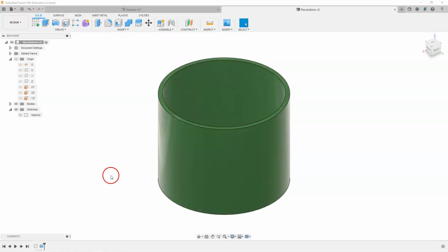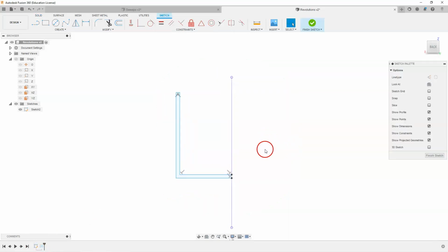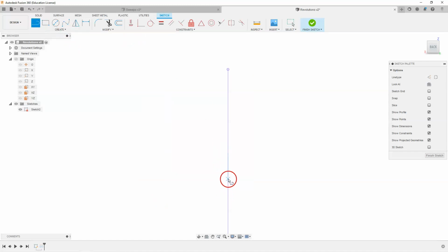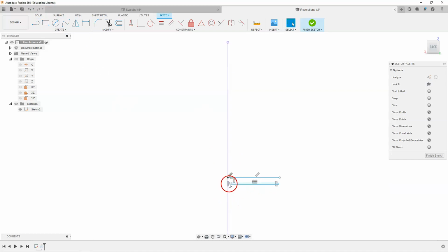This is a pretty simple shape. I'm just going to demonstrate how you can get some pretty creative shapes out of that. So going to go into my sketch profile here, and I'm going to change that to something a little more creative. I put a base on there. That means when it rotates around this axis, it's going to be solid all the way along the bottom. If I wanted a little hole gap on a little hole at the bottom, I would not want to touch that. I would want that line to be separated from there. So I want mine to be completely filled at the bottom when it rotates around.